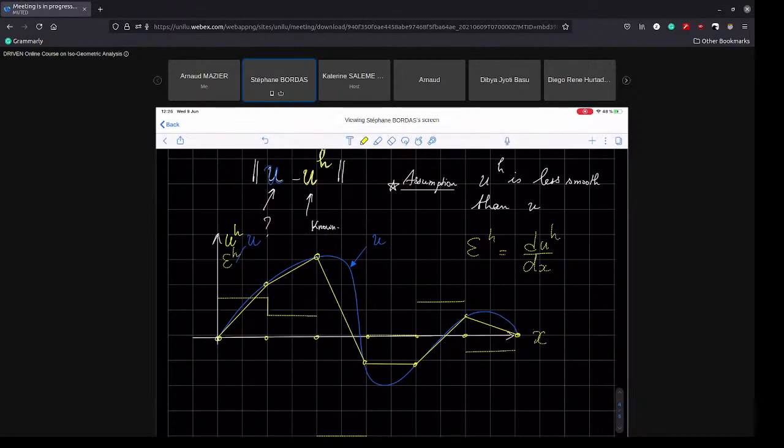You measure how big these steps are. And if the steps are big, as is the case here, for example, then you say, probably the solution is not that efficient, not that correct. So I need to refine this thing. So that's what you do. You just measure the jumps.